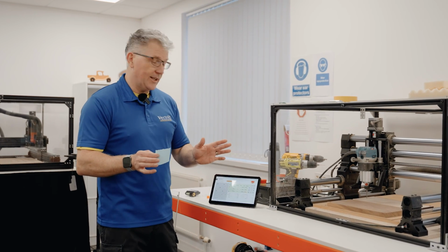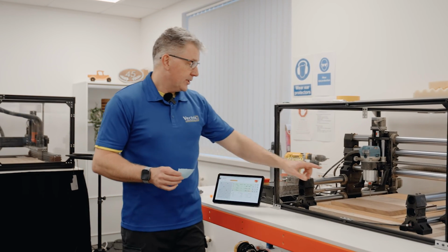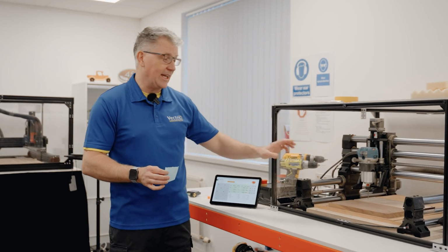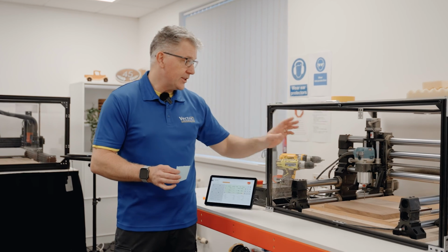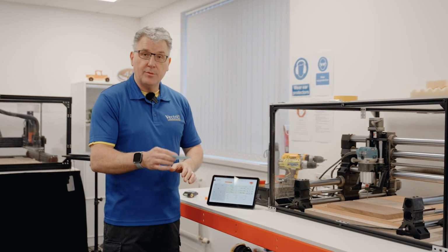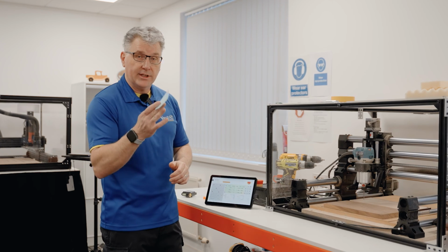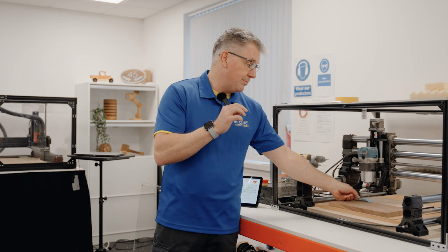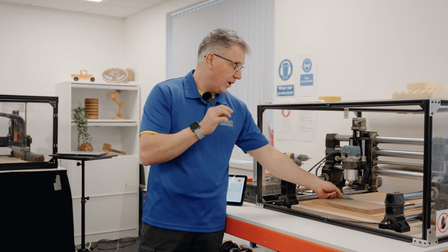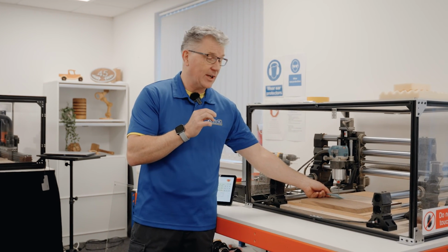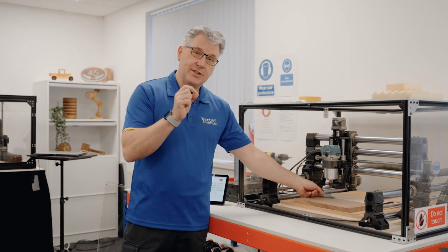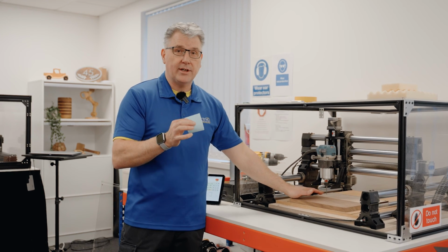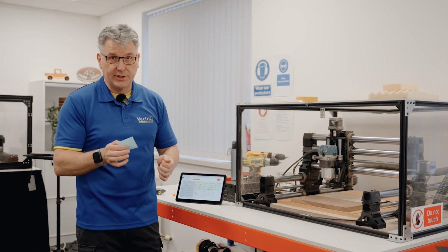Okay, so I've already gone ahead and set my XY datum to where I have the arrow on the piece of maple. Moved it back just a little bit, and this is where I'm going to set my Z0. Because this machine doesn't have a touch plate, I'm going to use the old-fashioned paper method, which literally is me putting a piece of paper on the material and nudging down the bit until it just barely touches it. That will let me know that it's only the thickness of a piece of paper away from the top of my wood. I'm going to do that every time I change out my bit instead of using a touch plate.